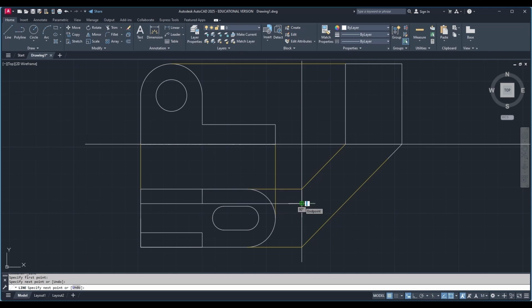Okay. Now I'll project these slot points. Again for here, I will position it above the XY line, tab option, then 45, then hitting enter. Again for this also, I will get it up to here, then position it above the XY line, use tab option, 45-degree, hitting enter.